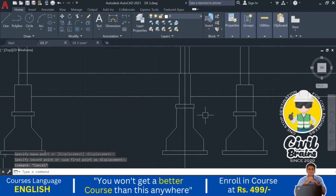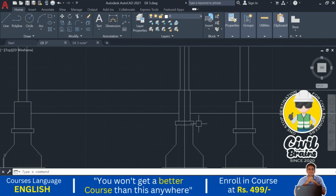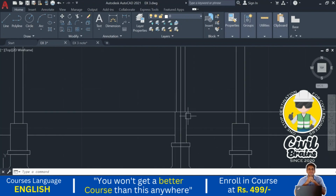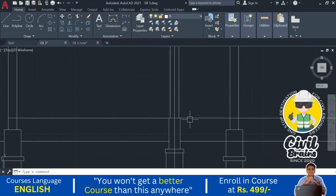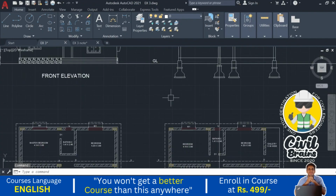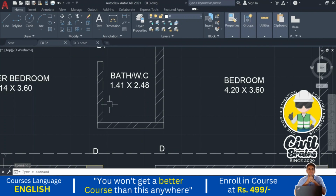So here you can see this one, width of the trench we have considered 0.5, and above that one 0.3 masonry wall till the plinth level, and above the plinth level what is the thickness of the wall. So here I just come to the plan. So above the plinth level the thickness of the wall is 0.15, correct?